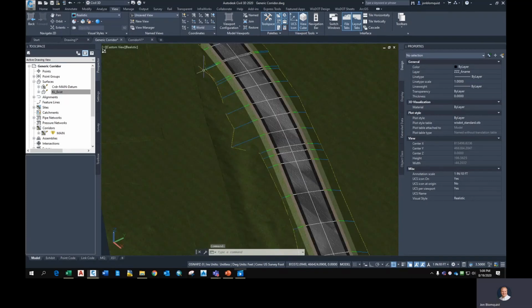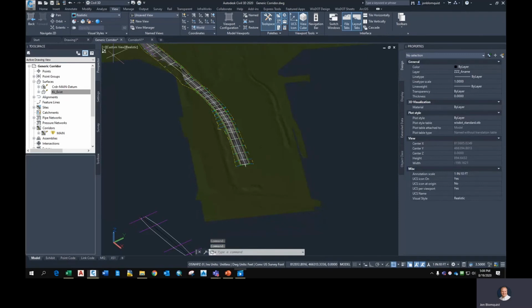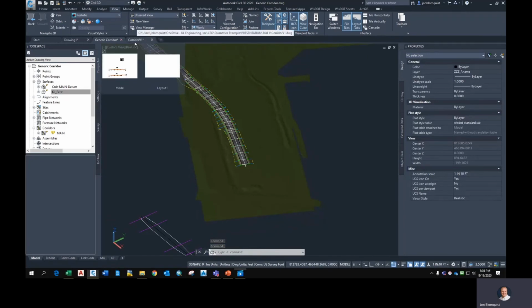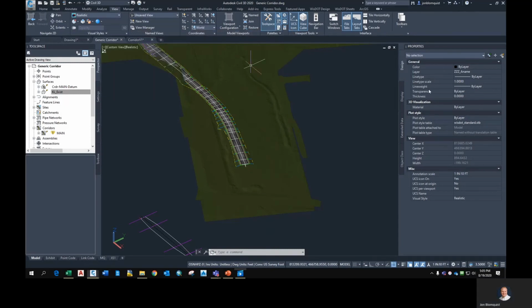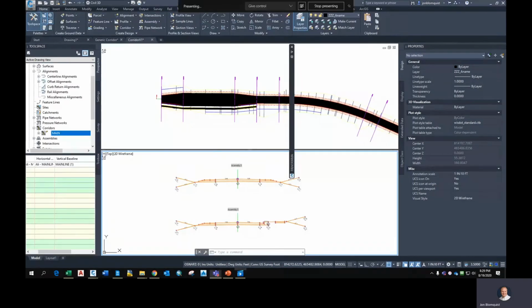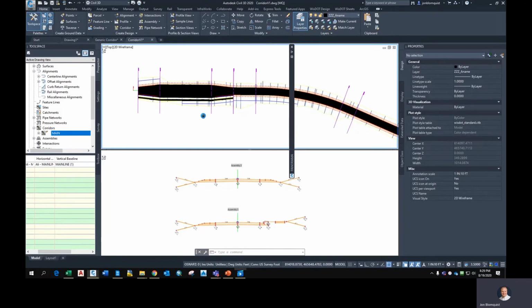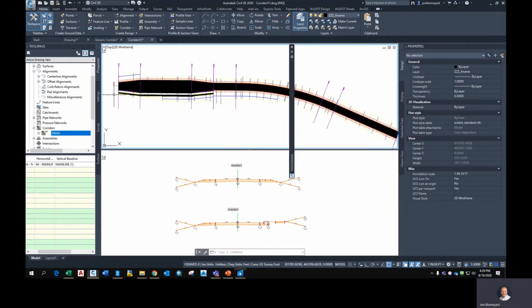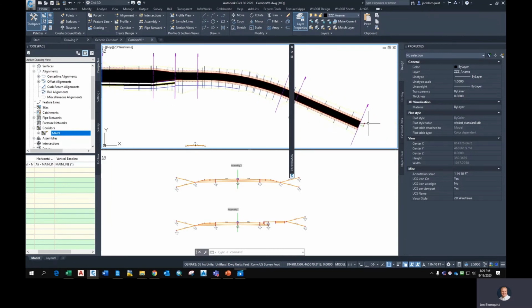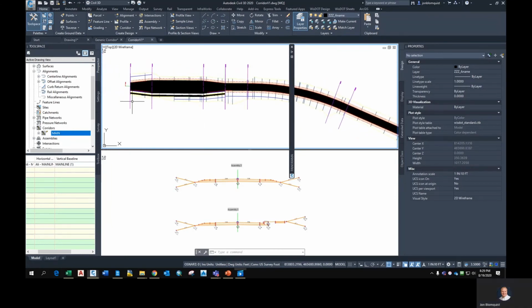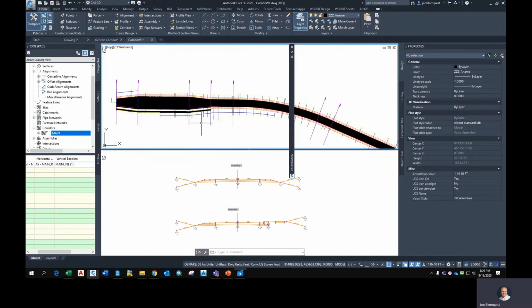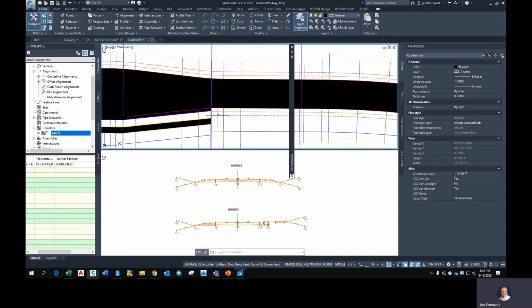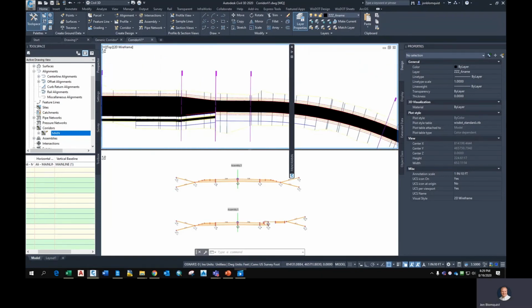and rendering. So I'll exit out of that and get back into our corridor file, and we'll go through our computing of the volumes. We're getting a little bit glitchy, so I exited out of the program and got back in. Before I started recording again, I made a couple of corrections. I had to correct the end limits to match up with what the pavement file was. And I also created a datum surface associated with the corridor so that we could create a materials list from it. I also inserted scan lines.